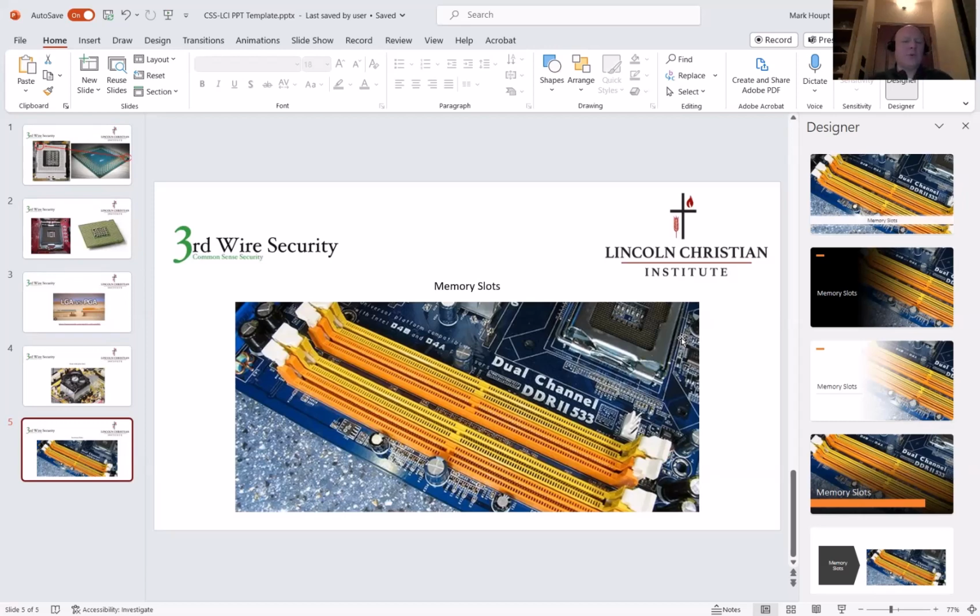So the way that you would put this in is first of all, align your memory with the slot there, and then make sure that line that's in the middle is lined up with your memory chip or the memory card. And then on either edge of your memory, you would just gently press down, and you're going to have to give a little bit of force, but enough that you'll hear it click in place usually, or feel it click in place.